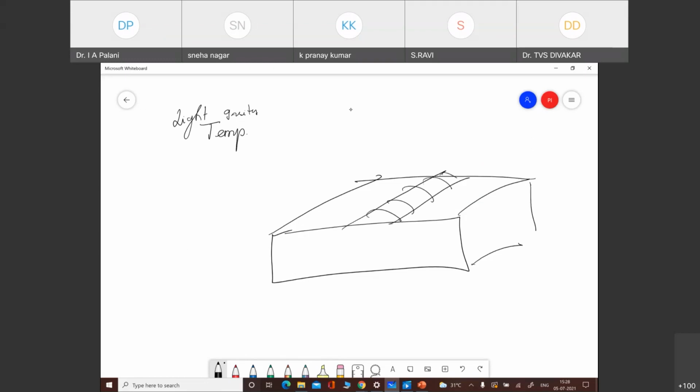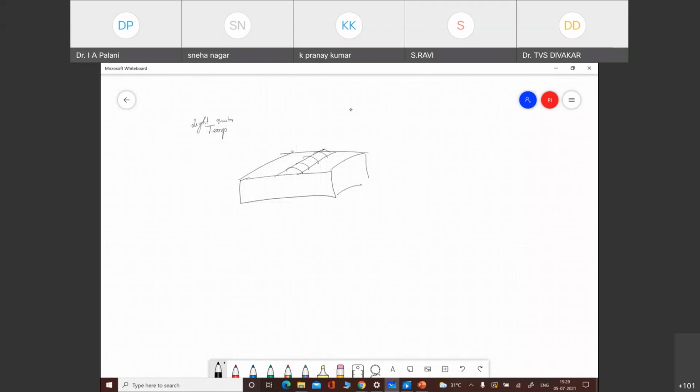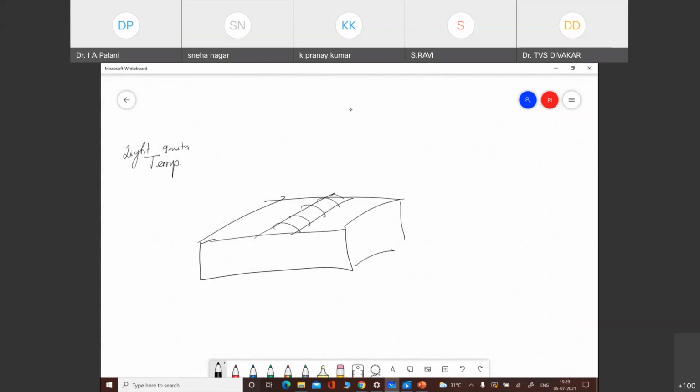And I have a weld bead over here. Through this weld bead, I want to measure the temperature of this weld bead. Normally what people used to do is put a thermocouple on this and try to measure it. But there is one option, which is on a very good phase and has a direct relevance towards optomechatronic systems, which we call the time resolved reflectivity technique.